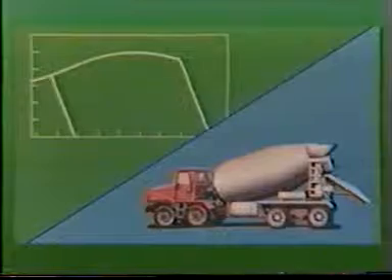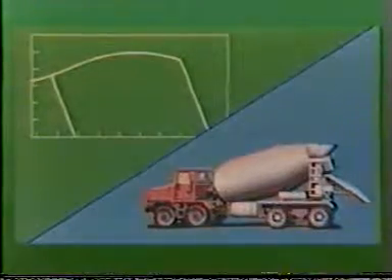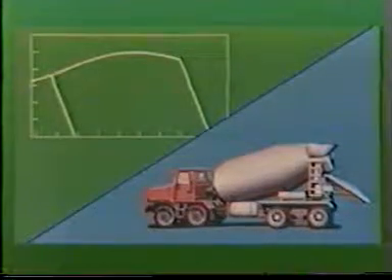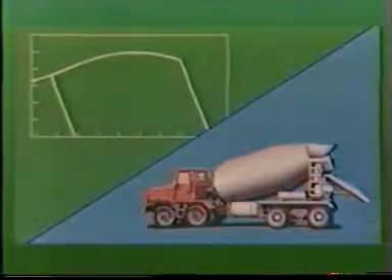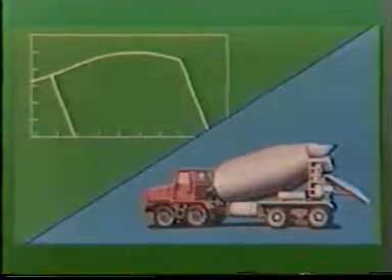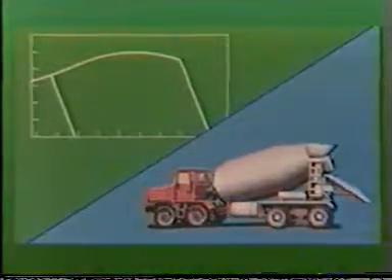The QSK19 fuel system offers up two intermediate speed control settings. In an intermediate speed control mode, the engine speed is controlled to a pre-programmed value regardless of throttle position. A separate droop percentage can be set which applies to all switched intermediate speeds and will be in force while the engine is in intermediate speed control.